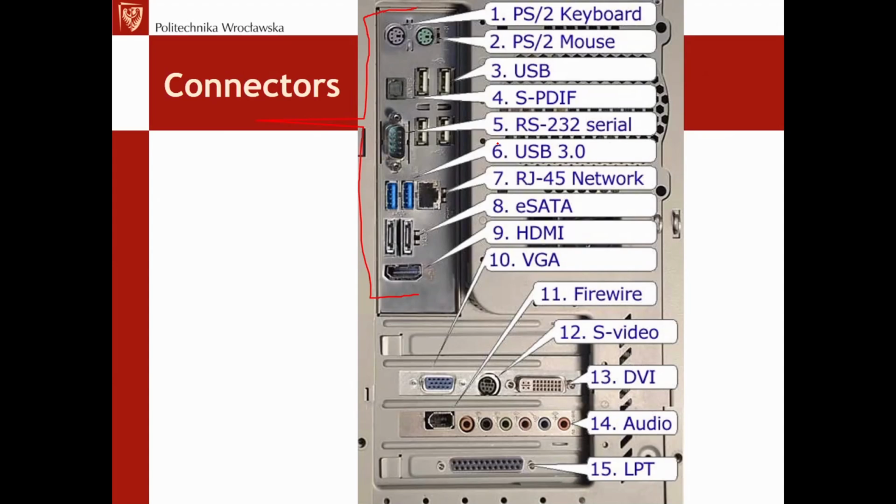It has to be considered already during the PCB design phase, and it cannot usually be left unattended until the very end of our design procedure, because of the connectors themselves, as can be seen here. Sometimes the connectors are very nice in that you can mount them directly on the case, which is nice because you don't need to think very much about the electromechanical construction of your PCB and its integration with the case.